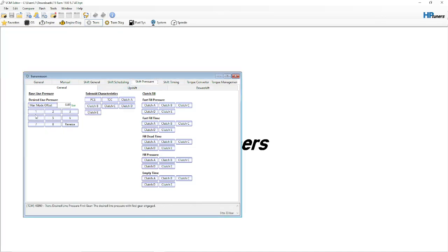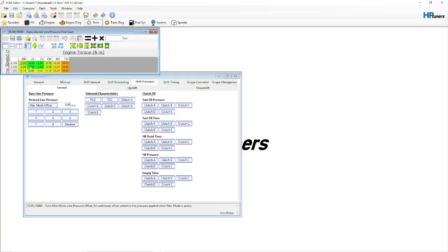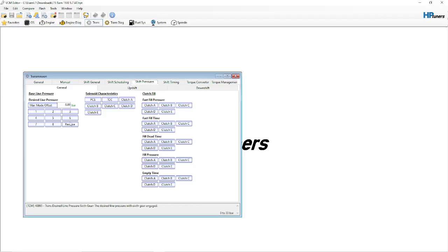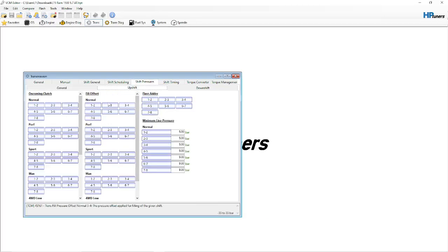So that then you get your baseline pressures and everything. This will actuate how much pressure is applied on the shift solenoids, on the valve body, on the clutch packs and the steels inside the transmission, the lockup of the actual clutches themselves. This will typically be your 1, 2, 3, 4, and then if you have a 5 or an overdrive, these you typically won't have to worry too much about. It's filling, it's doing its job.